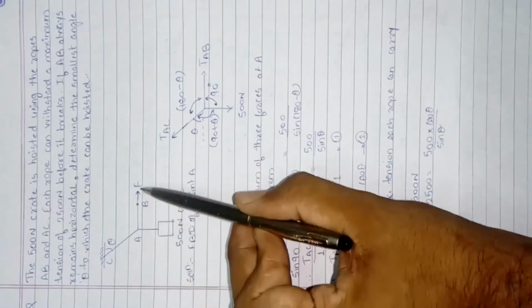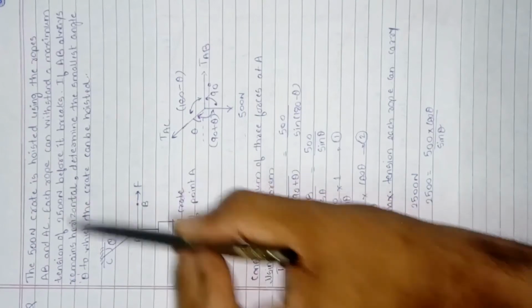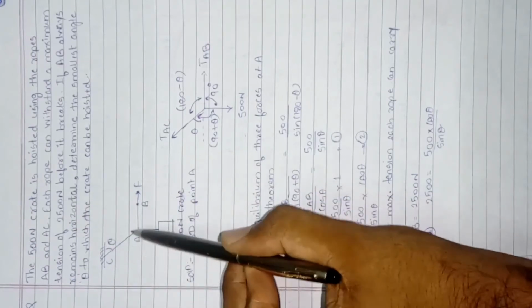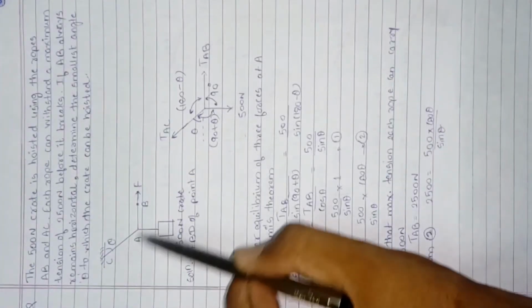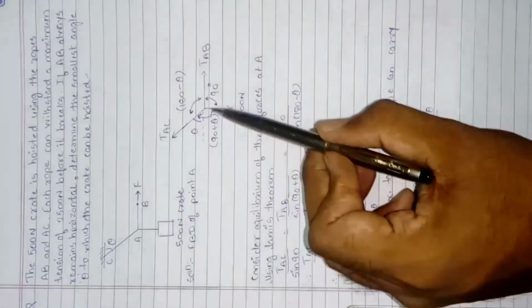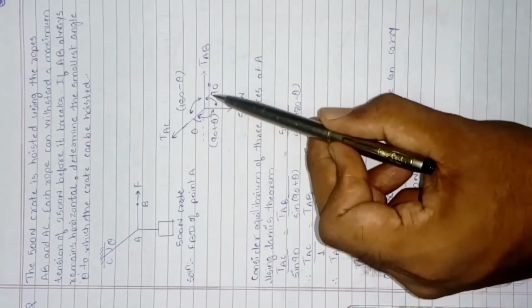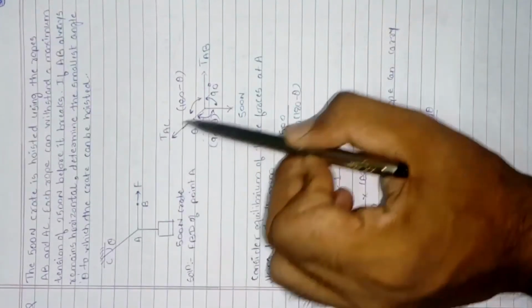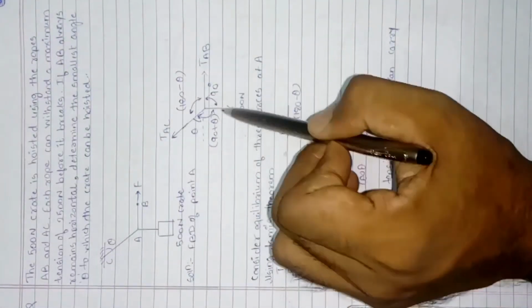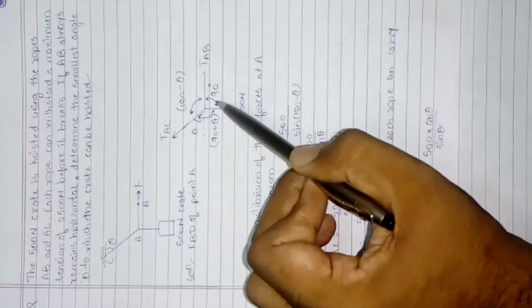If in either of these cables, AB or AC, the value is more than 2500, it will break and the system will not remain in equilibrium. Now here there are three concurrent forces, TAC, TAB and 500 Newton, acting at point A. The system is in equilibrium. Also we know the angles made by the three forces. Here this is the angle theta, the same will be the angle over here. We are also finding the remaining angles.